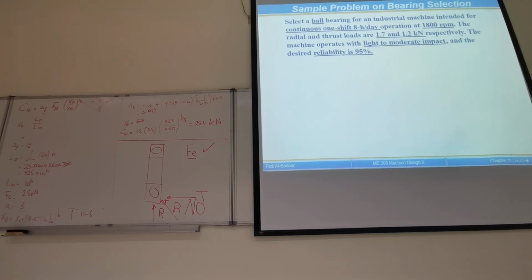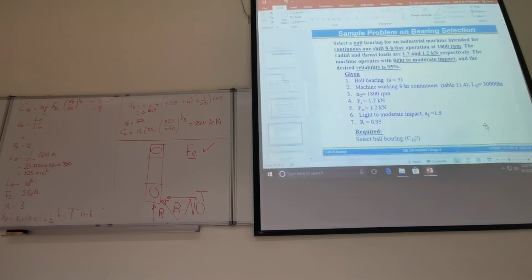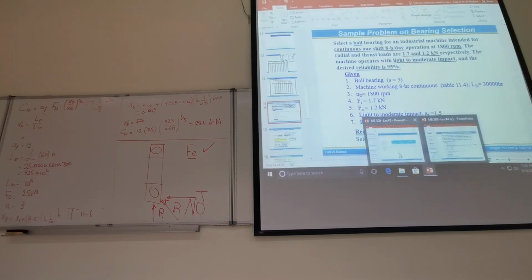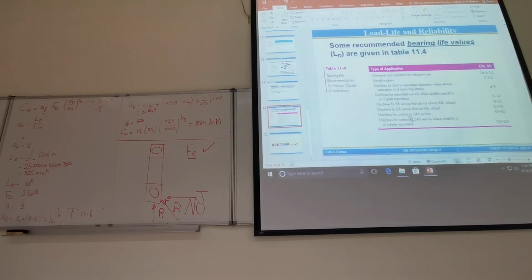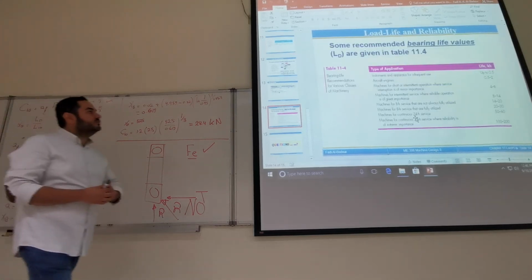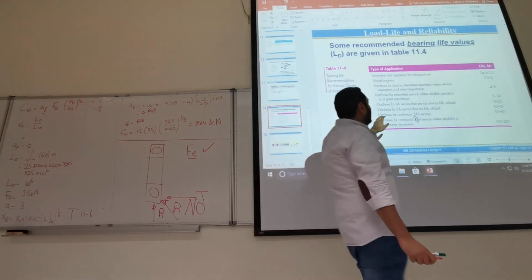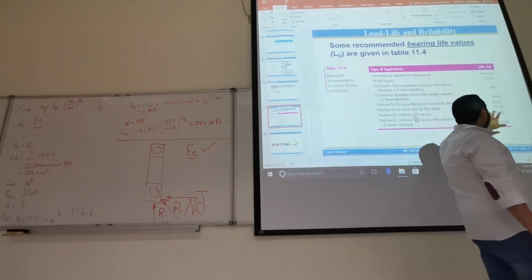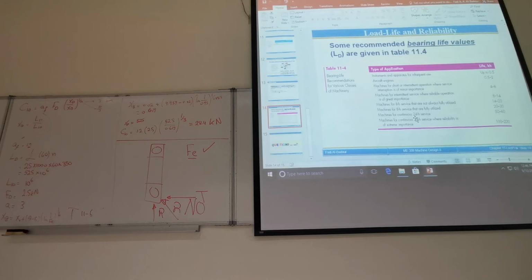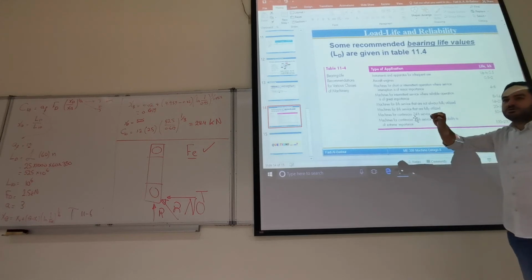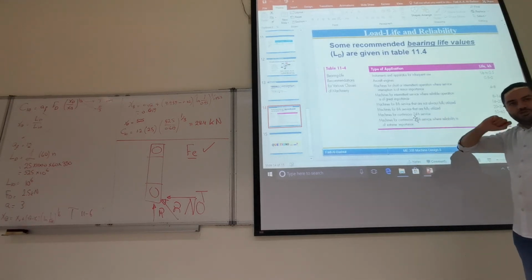in this particular case, we go and consult the recommendation. We have a table for recommended life. Table 11.4 gives you the application and the recommended life. Recommended life here is in kilo hours. For our case in the problem, he's saying 8 hours a day in a continuous fashion.